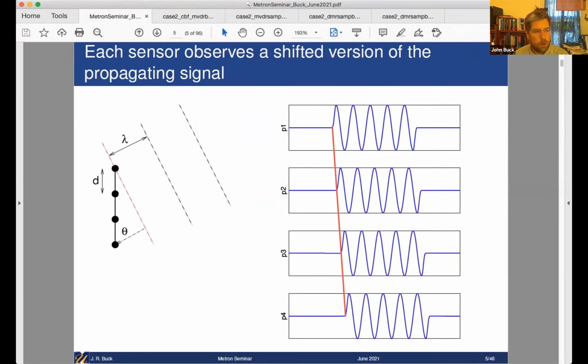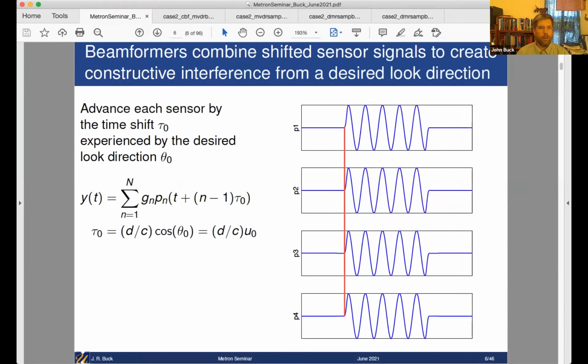We're going to talk conceptually about that first, and then I'll show you the mathematical formula. So when I want to beamform with an array of sensors, what I want to do is figure out how to shift and scale the sensors and then add them together to get a single output. For this very simple case, if I have some hypothesized direction the signal may be coming from, informally we often call that the look direction, I work out what the time delay would be for that look direction. I shift each signal to the left by the right amount for that direction so that any energy coming from that direction is all lined up.